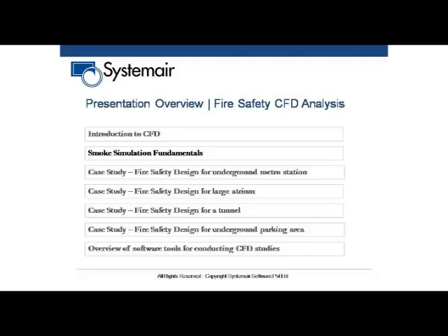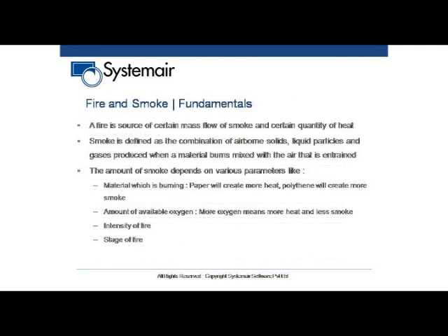The typical application we are discussing right now is smoke simulation. The fundamental is that a fire of a certain size creates smoke and it creates heat. Both can be simulated using CFD: how much smoke is being generated, how much heat is generated, and what path the smoke and heat are taking.